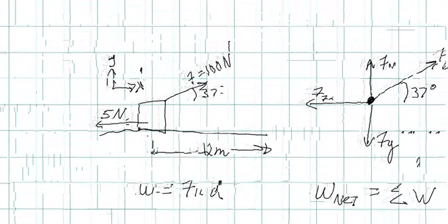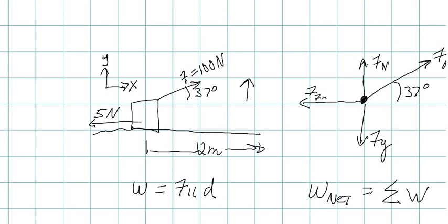There is a force that's actually pulling the box upward, and there's a force that's parallel with our distance that's pulling the box along. Yes, of course, the force that's pulling it upwards is actually going to reduce the normal force, which will change the value of the friction. Oh, I apologize. But we are given specifically in the problem that the frictional force acting on it is 50 newtons.